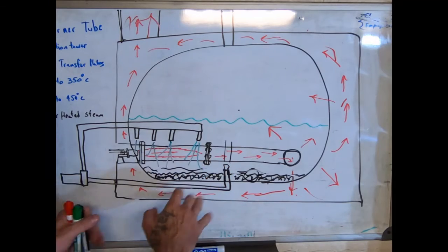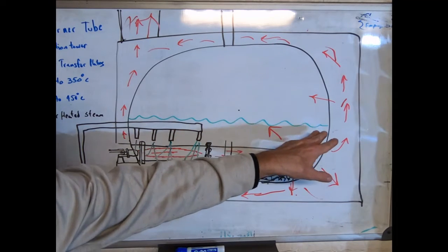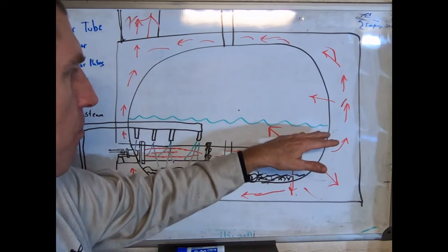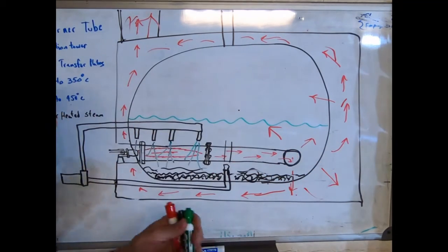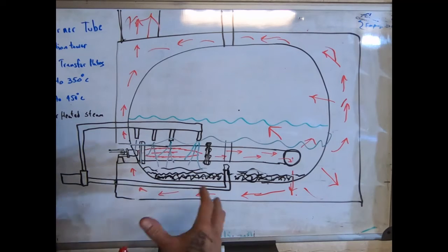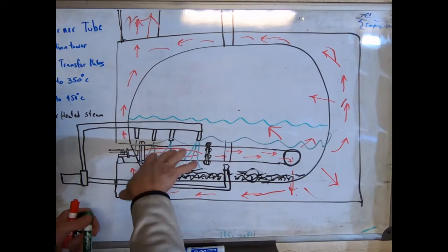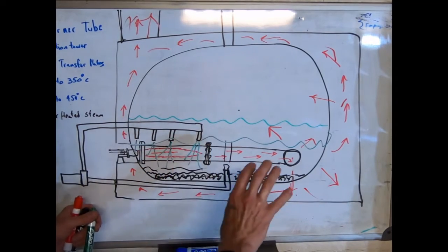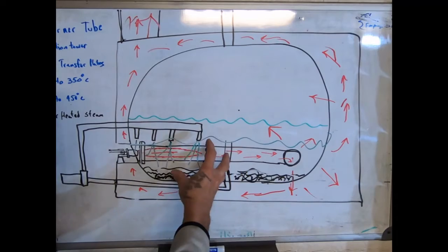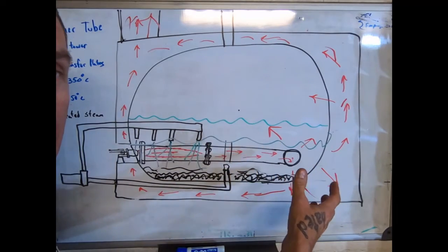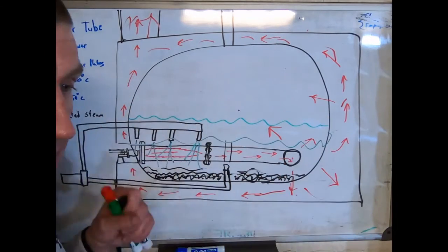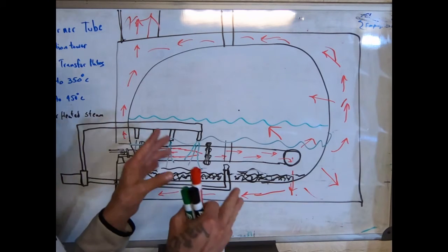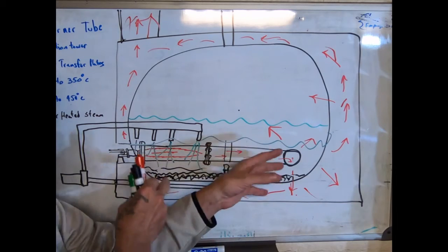Another thing we have to remember about the distillation process is as it progresses, the temperature or boiling point increases. Never want to let it get too far gone. And once we get it to the point where it needs to be at 350 or 300 degrees Celsius to boil, it actually needs to be extracted from this tank and put in a smaller processing tank that runs under vacuum. That's standard procedure for a chemical process of this nature.